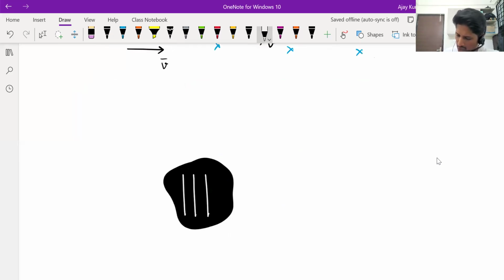See, if you make a groove like this, now the charge cannot go in this direction. It can't go from one side of the groove to the other side because in between there's no conductor. So you are preventing some eddy currents. You are reducing the eddy currents. So one way to reduce eddy currents in a conductor is to make grooves in the conductor. Create gaps. Don't allow charges to flow randomly.